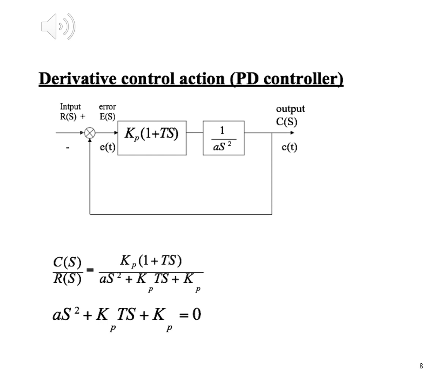Note that putting a PD controller will result in the transfer function shown, and this system originally is a type 2 second order system. Putting the PD controller does not affect the type nor the order of the system.